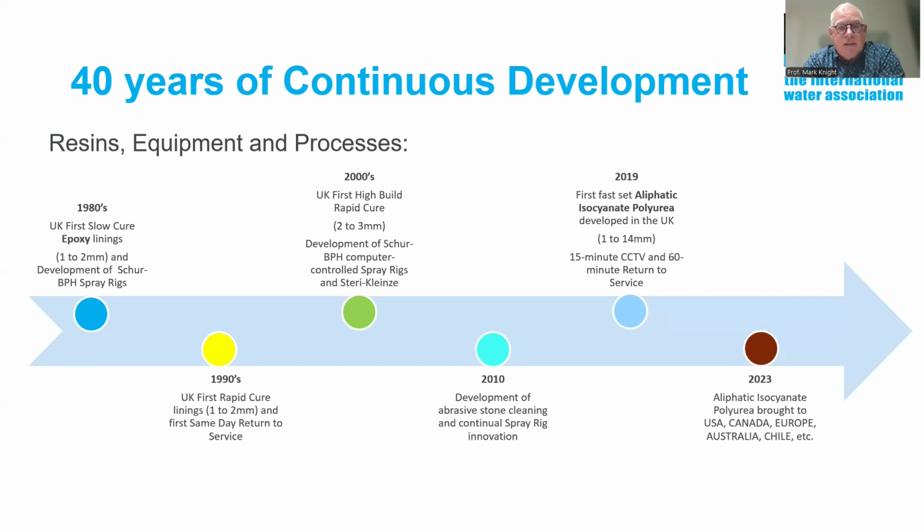As we advance into the 2010s, there were advances again in the spray equipment, innovation, and then abrasive stone cleaning came into the marketplace, which I'll show you a little bit later, in order to improve the cleaning and bond to the host pipe.